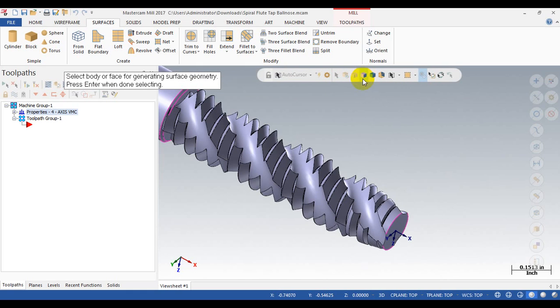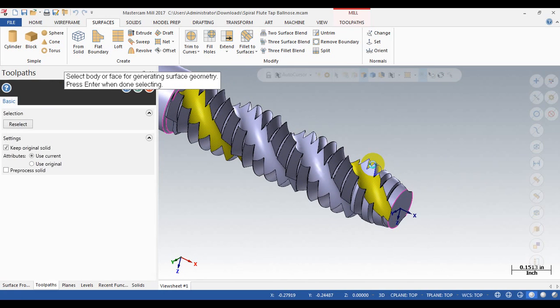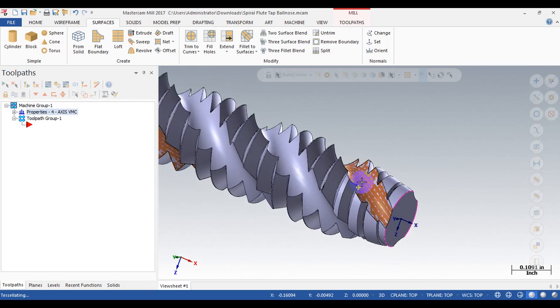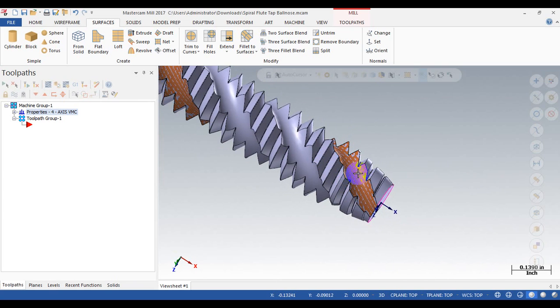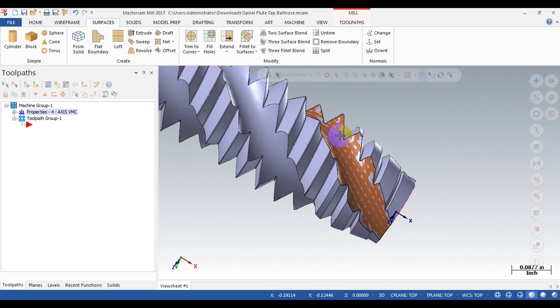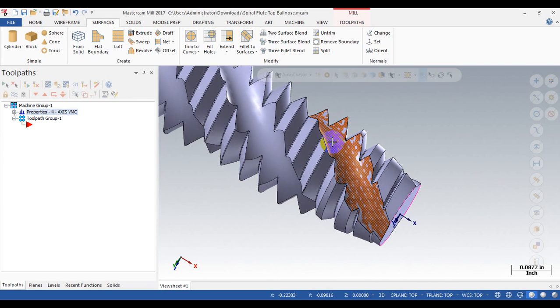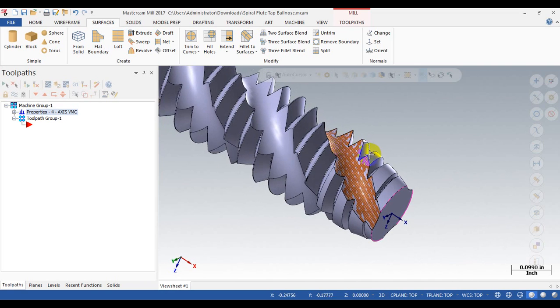You can see this is the solid selection option with the face selection activated, and then I click on this face and click OK. So you can see I just created a surface from our solid. But the surface is still interrupted. You can see you have the teeth profile. I don't want to have a bad surface like this.